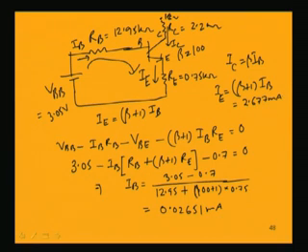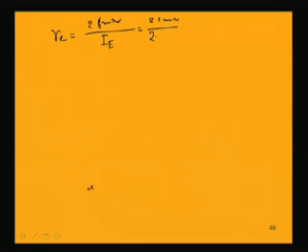Now we can find small re, 26 millivolt by capital IE, so 26 millivolt by 2.677 milliampere. If we calculate this value, it comes to 9.71 ohm. Now, after this we can find the required parameters like AV no load.